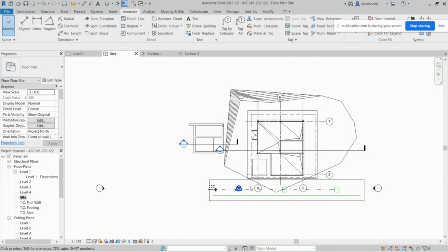Also, in addition to what you have, always keep them apart from each other. Usually they come close to the street, at the side of the street, and the street by itself is concave upward. You see that there is what you call camber in the street cross section. It's going to be highest in the middle, and it goes down on the left and on the right, in order for the water to run off efficiently on the sides and then drain afterward. What we have is a little different, because sometimes we have these manholes in the middle, and the water will just accumulate on them.